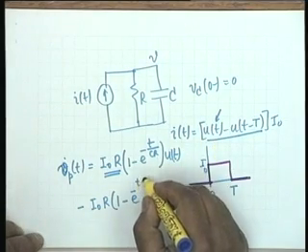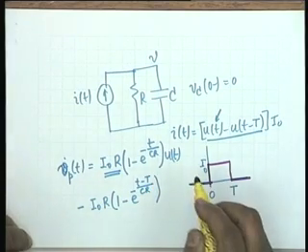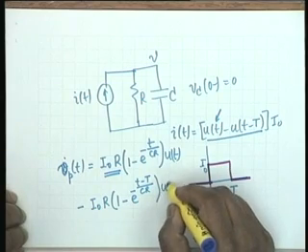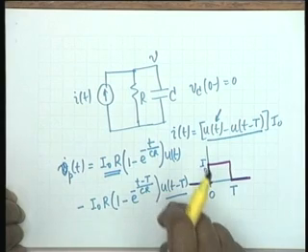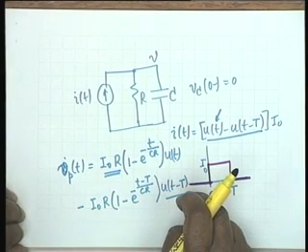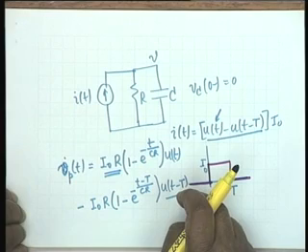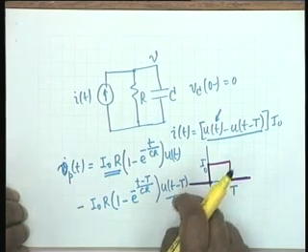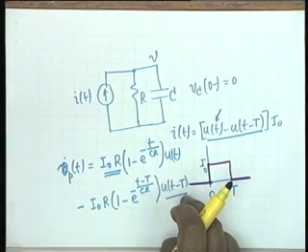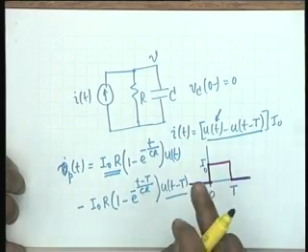So, minus (t minus capital T) divided by CR, multiplied by, instead of u(t), it would be u(t minus capital T). Now, why is this? How come you multiply this by u(t minus capital T)? That is because of causality, that is, the system is non-anticipatory. It cannot respond to u(t minus T) before u(t minus T) occurs in the scene. The previous response is due to u(t).